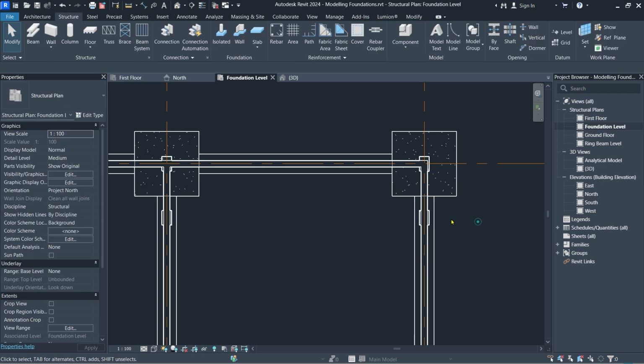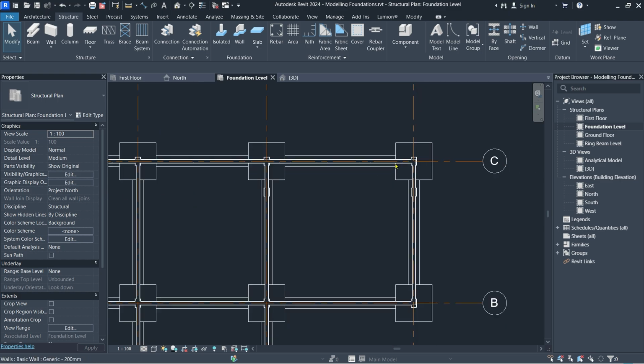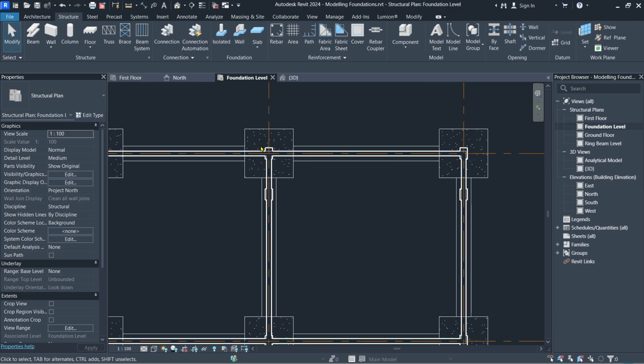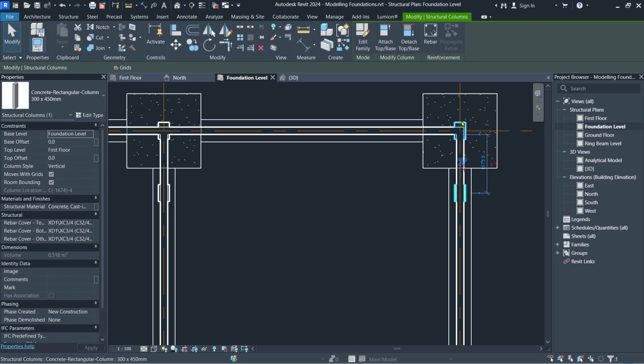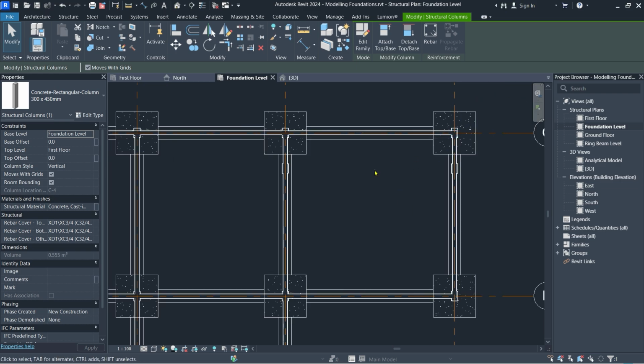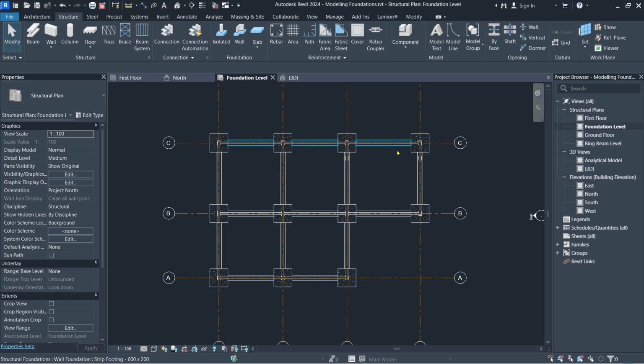like that. Now I want you to insert a combined footing as an assignment for this tutorial. Combined footing for these two, this and this. You can say that you'll have an offset of the column on all sides of, let me say, 1 meter on all sides. So that's up to you.